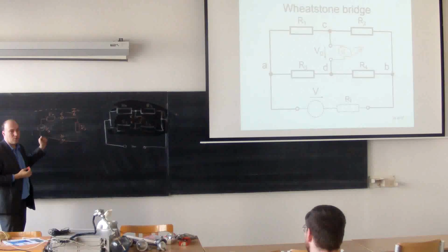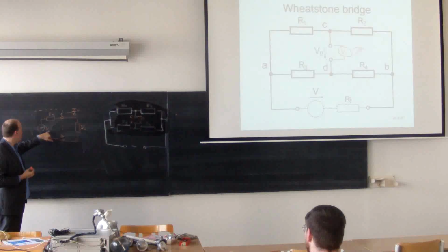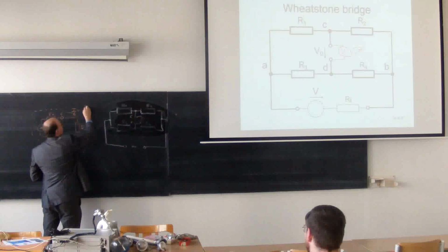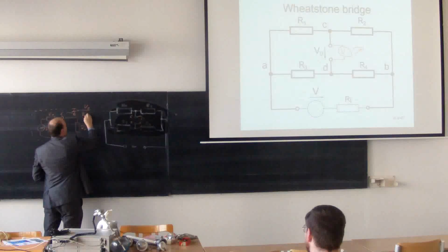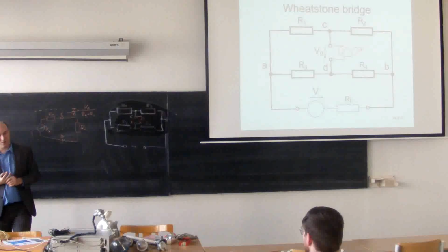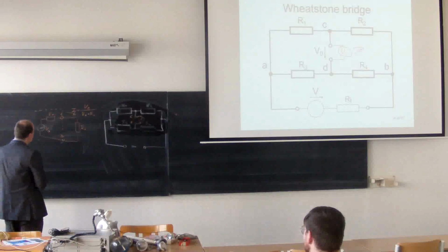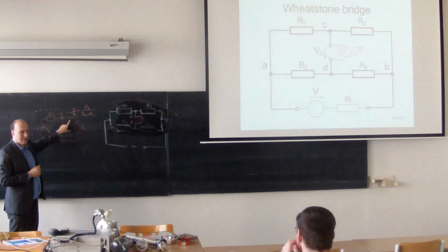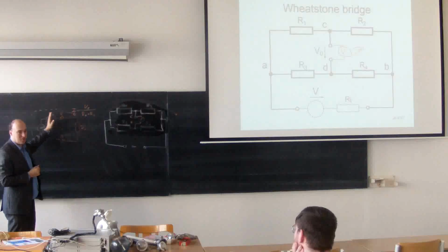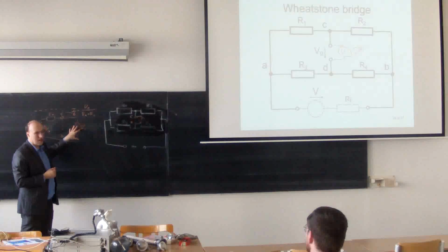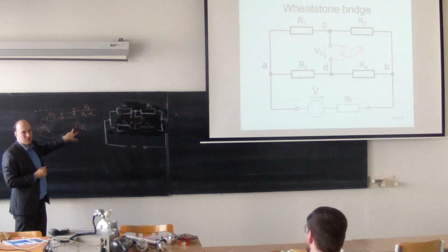So, according to Ohm's law, current will be voltage divided by RK plus RB, V0 over RK plus RB. So what does this equation mean? It means that the current that I measure depends not only on the internal properties of the bridge, but it depends also on the instrument I use to measure the output.